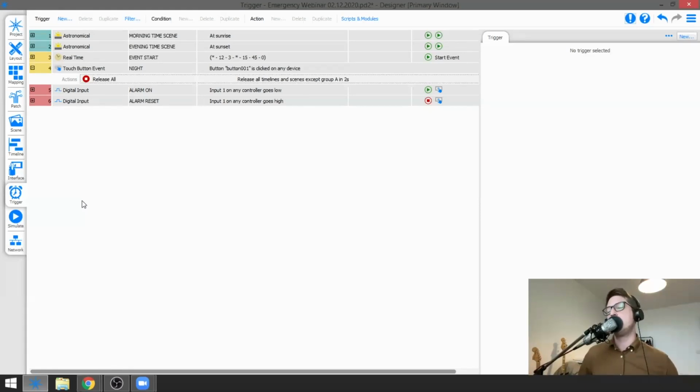So typically speaking, we can do integration with lots of different things, such as UPSs as well. A lot of UPSs now have smart features where we can send a command over a serial connection or network, and obviously that can then control the power. But as I said, if you want to do it straight from Pharos, then you need to be wary that you can do it with a Rio output, but it needs to be under 48 volts.